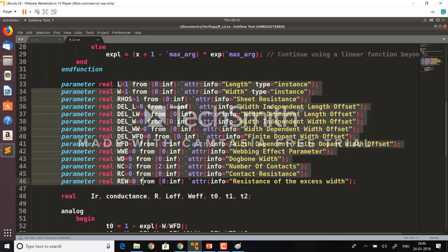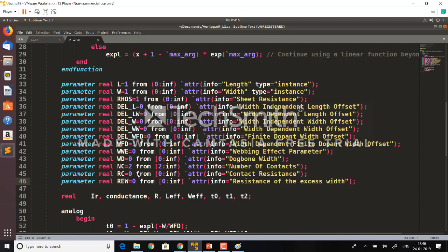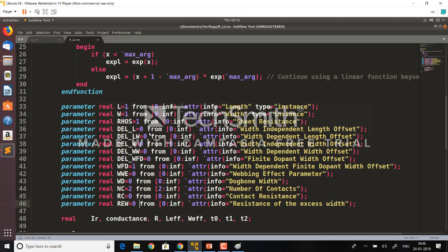So these are the default values. You can set anything you want. Yeah, these equal to. So you're assigning something. This is default. Normally when we make a model, we assign parameters in which everything is within bounds. Like if we do a MOSFET model, we set the parameters such that your S parameters are within bounds, your IV curves are within bounds. Okay, nothing is very exotic. You don't see crazy S parameters. Everything should be normal, looking normal. That's all.